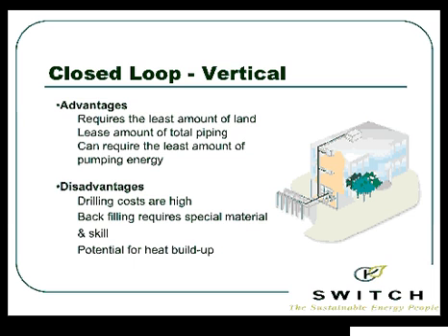Closed loop is traditionally the result of that. We end up moving away from open loop designs and going to closed loop. The majority of ground source heat pump systems are going to be closed loop systems. First one, of course, is vertical. We can talk about a vertical system. Requires less land than the next couple, which are horizontal type systems, okay?